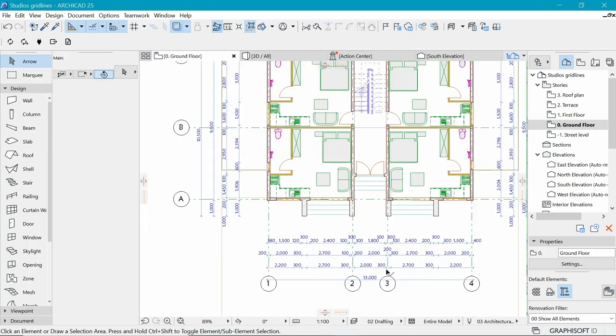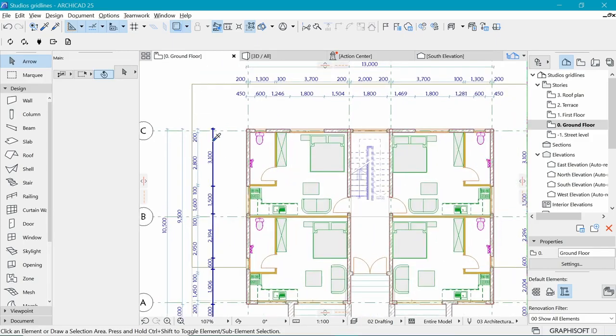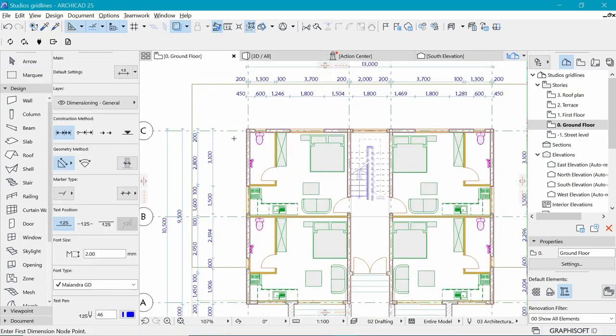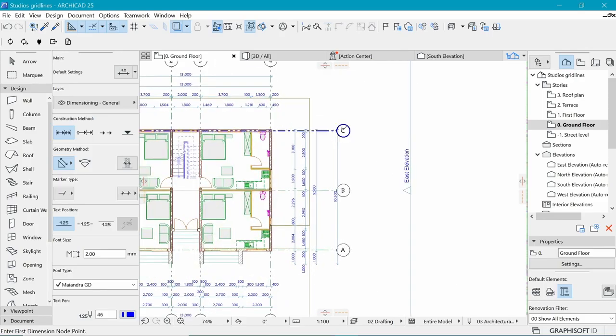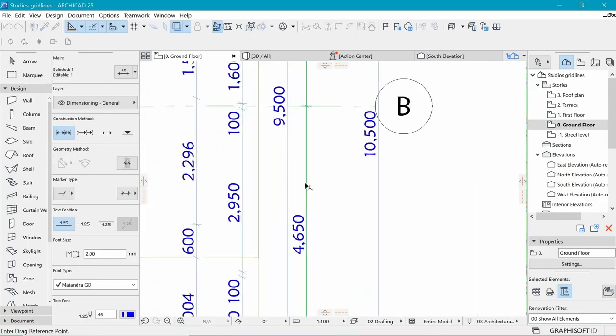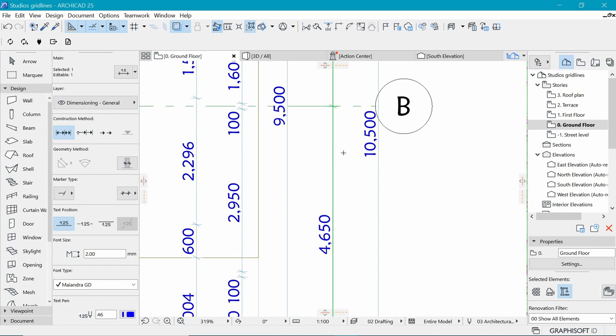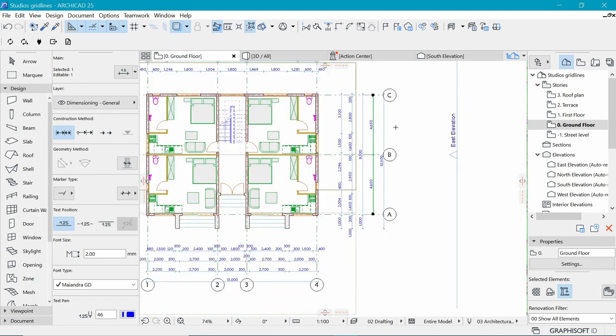I don't know, I think we lost it, but it's fine. I can always pick and dimension them manually, so we can have these 4 parts and put them somewhere here. And of course, in order to have it uniformly distributed, I will bring it here and use this distance to offset it, the 800, such that now these are uniformly spread out.